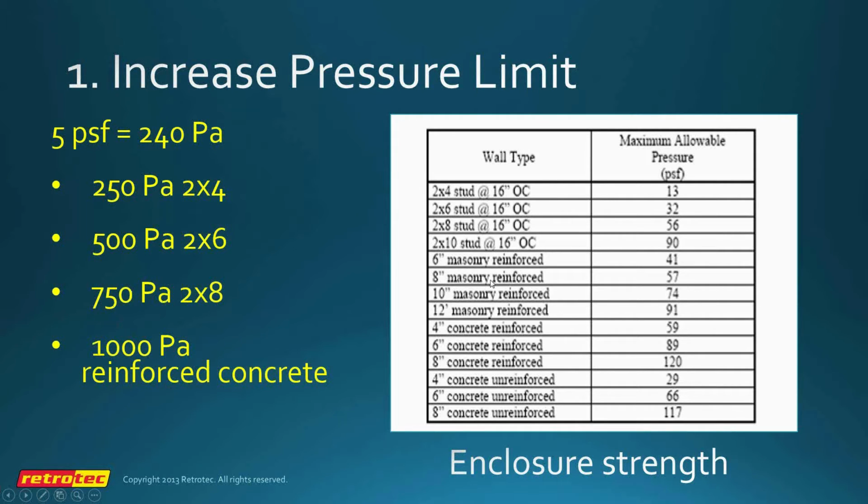We do have to be careful with concrete block. Concrete blocks that are just sitting there basically without any reinforcing can actually be knocked over relatively easily, and some of the failures have happened with concrete block walls. So if we have concrete block walls, we need to have some reinforcing in there, and they do need to be attached to the enclosure top and bottom. If that's the case, and they're reinforced, we're pretty confident they'll accept 1,000 pascals. If they're not, the concrete blocks are just sitting there, they'll probably handle 250 okay, maybe even 500, but more than that could be a problem.